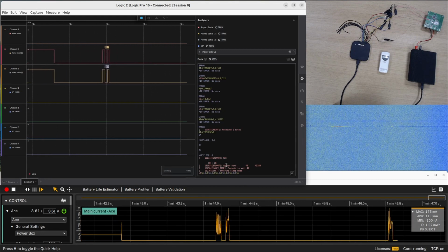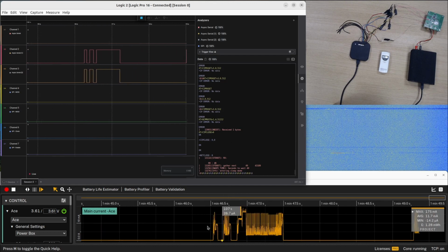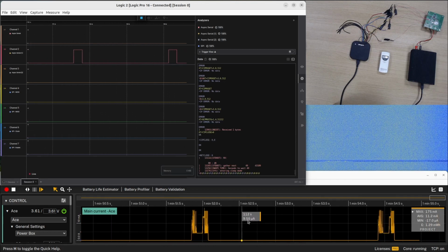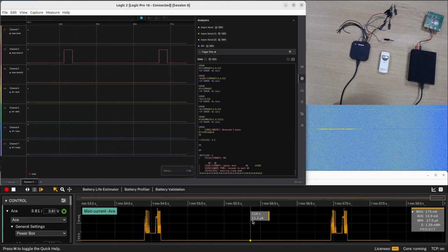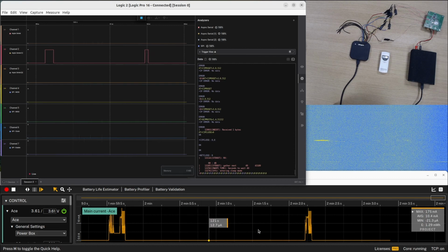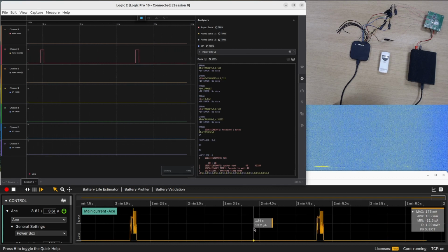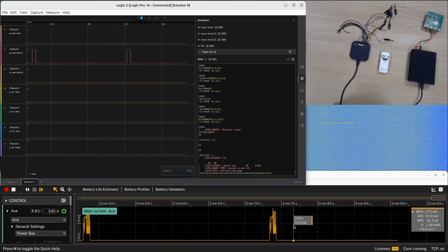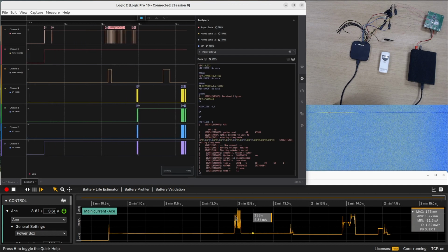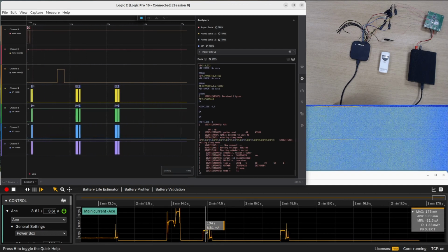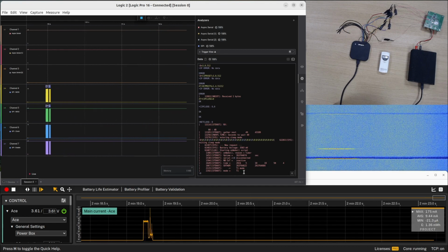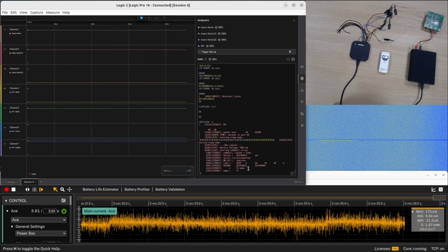And what we will check first is the power consumption of the device, which is now close to 0 because it is in the sleep mode. Just the narrowband IoT module is talking to the network, but it will go to sleep after a while as well. We can see that based on the power consumption, you see what is happening with the device. Now the device woke up, and you can see that the power consumption went up, and now the reception in wireless M-bus T1 mode was enabled.